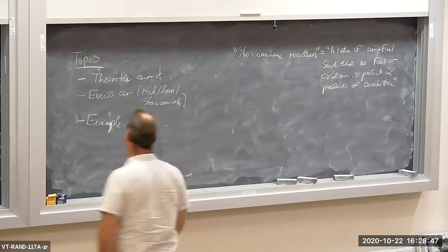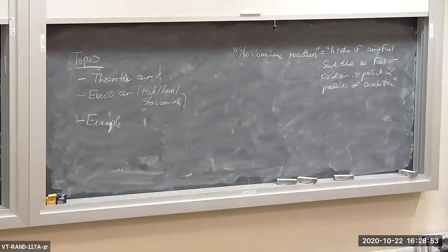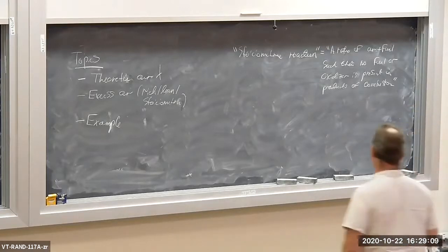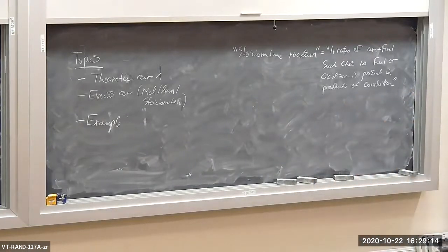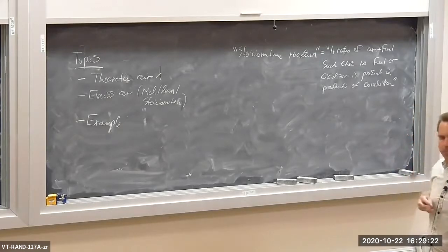Basically, it's the reaction mechanism including the nitrogen component. So if you write your reaction mechanism, which is completely balanced, and you write the N2 in there as well, then you'll have a stoichiometric reaction. So the example that we did last time was a stoichiometric reaction. As you recall, the combustion of butane in air had no butane in the exhaust or the products, no oxygen in the products. So that was technically a stoichiometric reaction. The example we just did was a stoichiometric reaction.